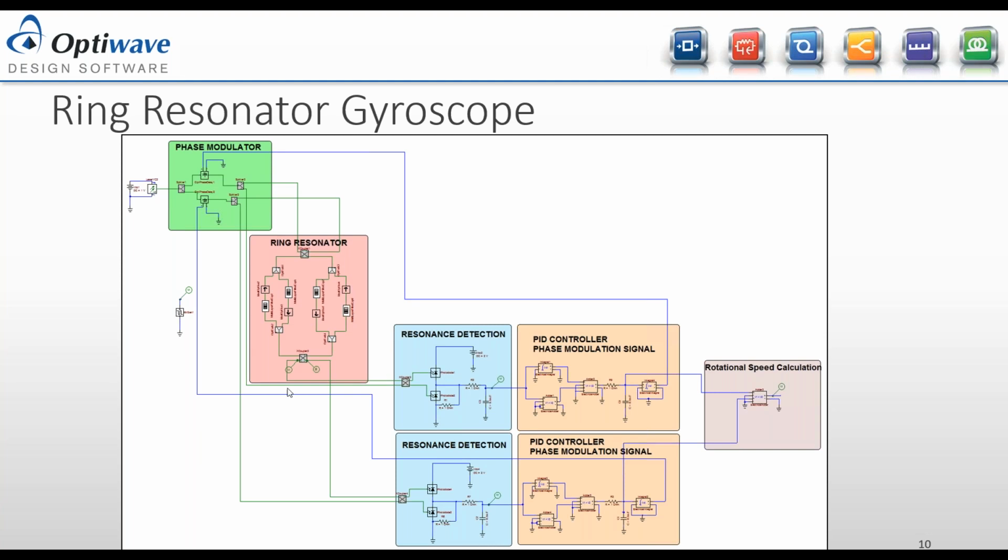That is the most important part of this gyroscope. This gyroscope is built only for one axis. When you have rotation, and a signal traveling around this ring resonator, clockwise or counterclockwise, due to the Sagnac effect, the signal traveling around the ring resonator sees either a longer or a shorter path length, which in turn means that the effective resonant frequency of the resonator shifts.